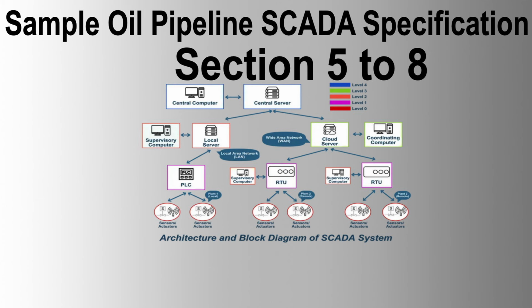5.2 RTU features. Dual microprocessor-based modular electronic control device equipped with I/O terminals suitable for direct connection to field wiring of analog and digital control and monitoring devices. Supports multiple standard SCADA protocols, such as Modbus, multiple RS-232C and RS-485 serial ports, each capable of carrying a different communication protocol. Ethernet ports, minimum of 4 Ethernet ports compatible with IEEE 802.3 100BASE-T specifications.